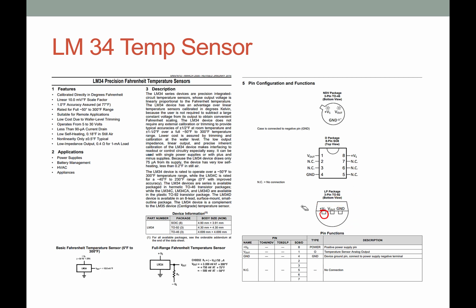So you're going to want to tie this lead to 5 volts, tie this to ground, and now make sure you tie the common lead of the 5 volt source to the ground on the board that you're using, because this ground should be the ground of the board, but you also want to tie the 2 together so that way you get the right 5 volts there.